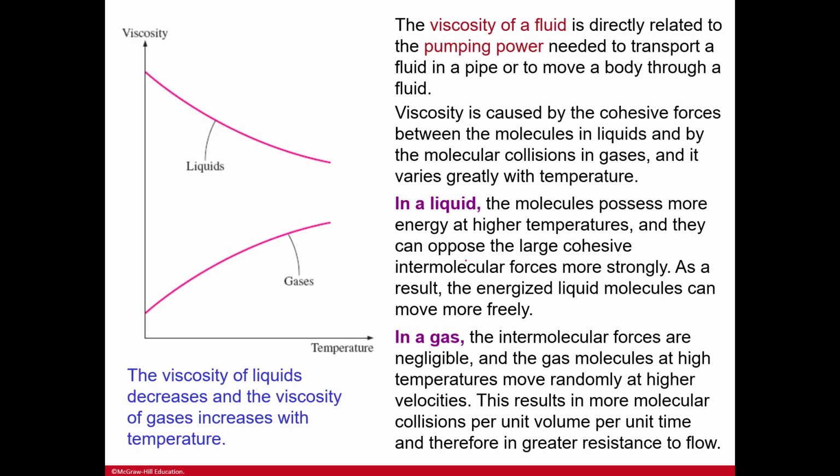Here you can see that behavior for viscosity over temperature between gases and liquids. The viscosity of liquids decreases and the viscosity of gases increases with temperature. The viscosity of a fluid is directly related to the pumping power needed to transport a fluid in a pipe or to move a body through a fluid. That's because fluids behave much more rationally when we're comparing them to gases.